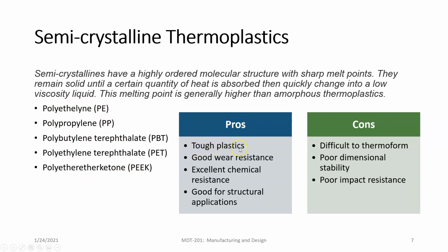Pros here: they're very tough plastics. Good wear resistance, excellent chemical resistance, good for structural applications. The cons here: they're difficult to thermoform. They have poor dimensional stability and poor impact resistance. All right.